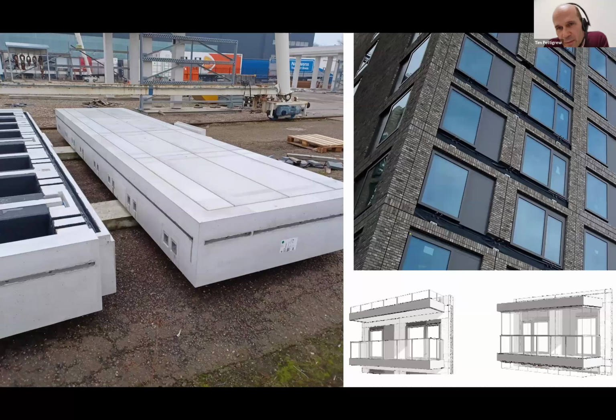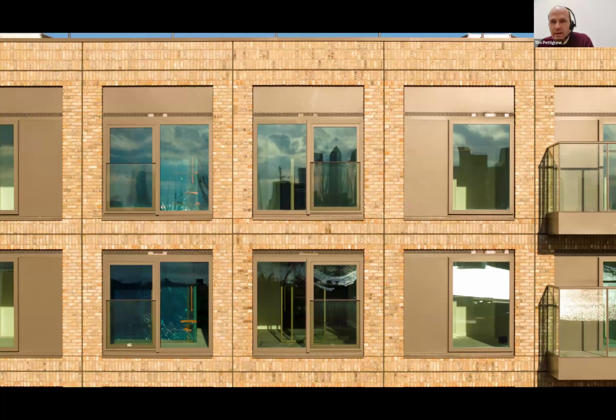We also did prefabricated concrete balconies on this. They were again lifted into place, connected, so drainage was built in, finishes were off-site, and it was a really, really successful system. As I said, it does create an aesthetic, and although we look at the movement joints and trying to pick that up, we did actually use the movement joint across the top in certain locations as well, and we worked on the whole system with the cladding contractor throughout this process.